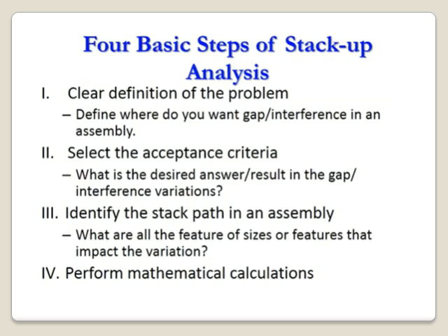Third one is identify the stack path in an assembly. What all features of size or features impact the variation? Whatever gap we are trying to figure out, we need to stack all the parts, and we need to see what variations might happen after manufacturing.